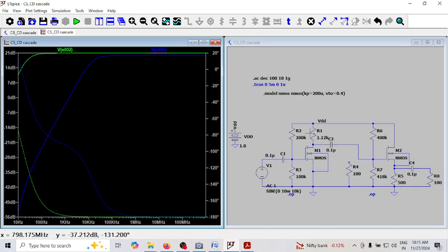That's where, in usual circuits in analog electronics, whenever you're driving less resistive loads, or whenever you want to deliver larger current, it is not possible to do it using only one stage. So you have to consider cascading stages, because the output impedance of the overall amplifier should be as small as possible. That will be achieved using this CD amplifier. If you see the output impedance of the CD amplifier, it is very less. That's what an ideal amplifier requires.